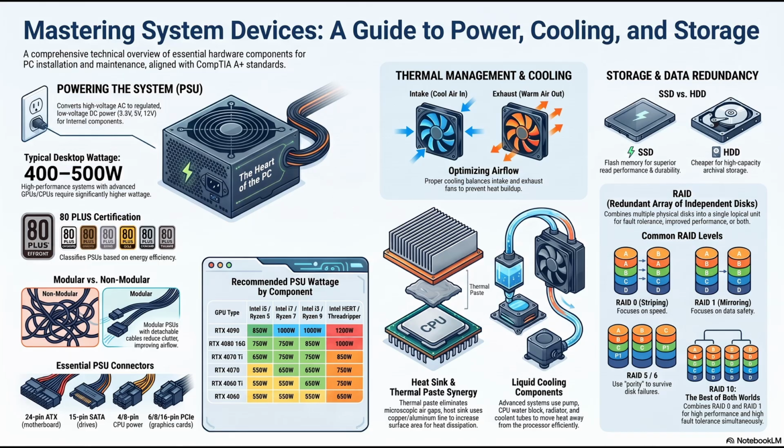The source outlines the leap from older asynchronous DRAM to SDRAM in 1993. The S stands for synchronous. Because before 1993, the memory and the processor were completely out of sync. Completely. The older RAM operated on its own internal timing. The ultra-fast CPU would send a request for data down to the RAM, and then the CPU would literally just sit there, idling in a wait state, burning power and doing nothing until the RAM eventually got around to serving up the data. It was catastrophically inefficient.